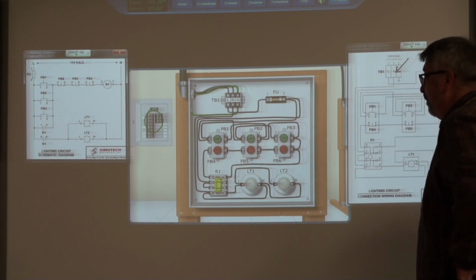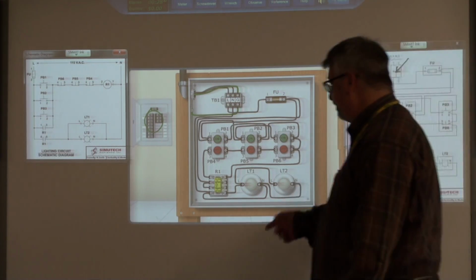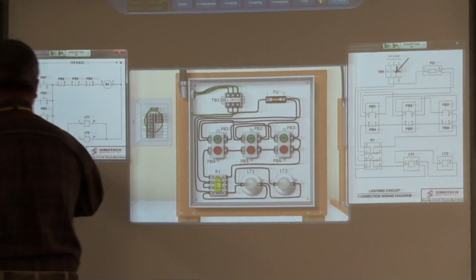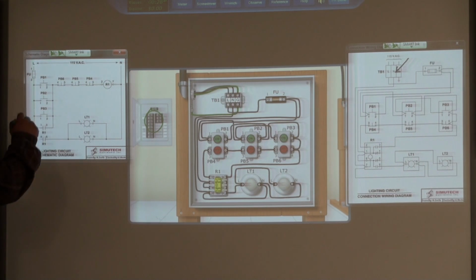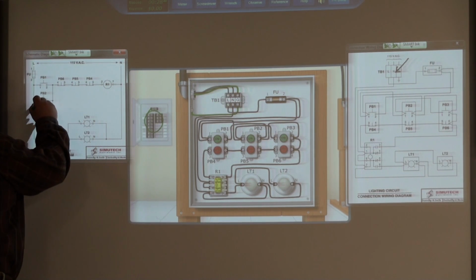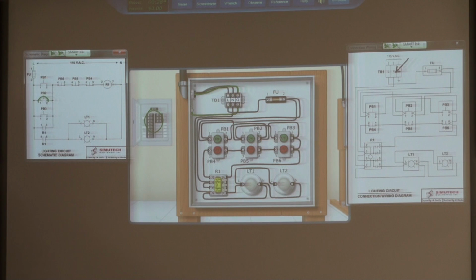Either way, it's something to do with getting power. So if any connection on the line side welds itself shut, you get that symptom, whether it's 1, 2, or 3. As long as you close the circuit, you're going to have juice. If PB2 suddenly welds across, what's our symptom? Same thing. The lights are on, right? They'll momentarily go off when you mash 1 and 3 off, or press the engage button. By welding that, we're really doing the same thing as that contactor, except we're doing it with the switch instead of the contacts of the relay.